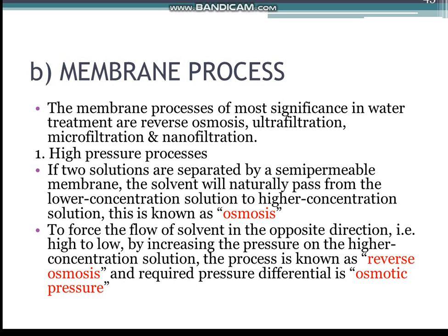First, high pressure processes. If two solutions are separated by a semi-permeable membrane, the solvent will naturally pass from the lower concentration solution to the higher concentration solution. This process, as we all know, is called osmosis. It is possible, however, to force the flow of solvent in the opposite direction, from the higher to the lower concentration, by increasing the pressure on the higher concentration solution. This process is known as reverse osmosis, and the required pressure differential is known as the osmotic pressure.